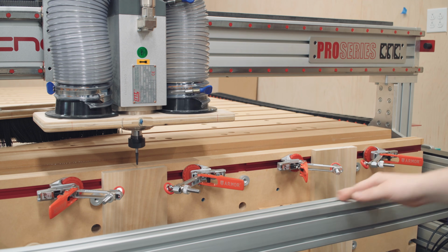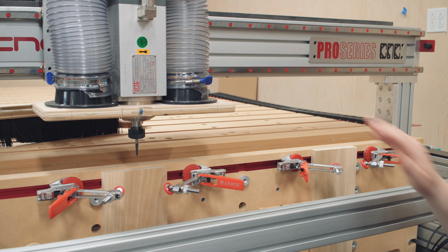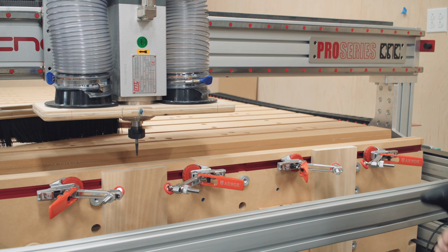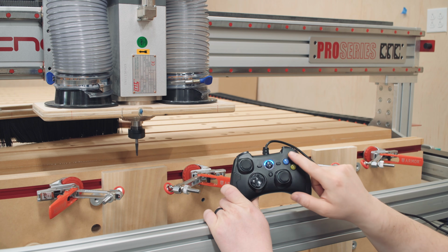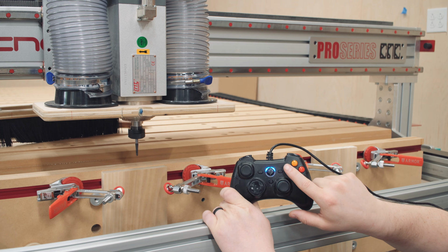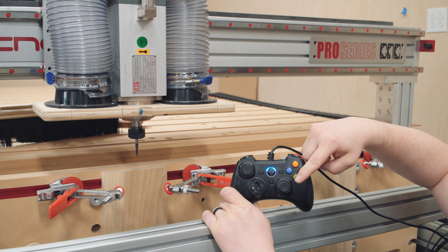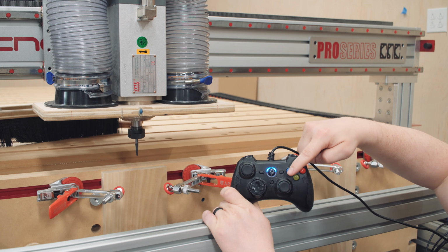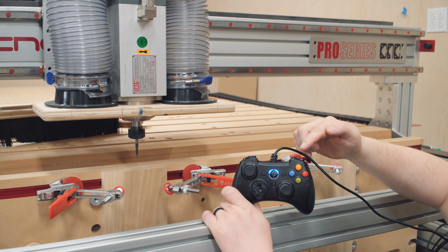So on the Mach4 screen, the MDI screen, manual data input, I typed in Z.75, cycle start, and it'll move it to a Z value of 0.75. And this is where everything starts as far as lining up all of your pieces. And it's also where this is super handy. So once again, these buttons on this side is slow travel. This side is high travel. This side is up. This side is down. Slow, fast, up, down. And then incrementally up, incrementally down, and that's very important.